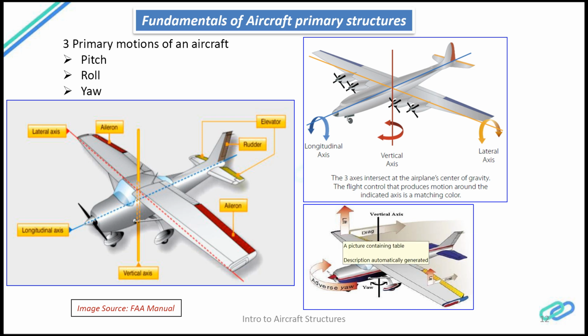And you can see the forces over here. The lift is generated on the wing surface, and drag simultaneously. Here you can see the picture. One of the ailerons has been up and the other aileron has been down. What would happen is, the one on the down side would produce more lift, and the one which is up will produce a small component of lift. So it is not equal and opposite. So whichever side is up, the aircraft will tend to roll to that side.